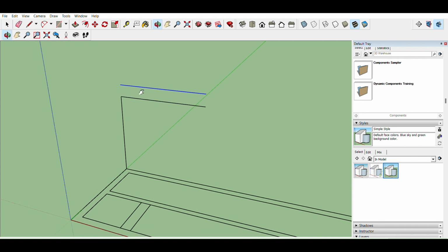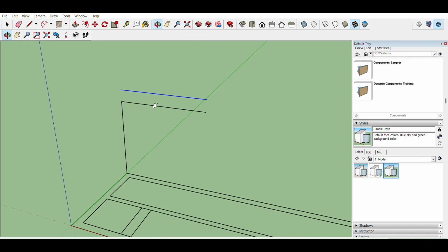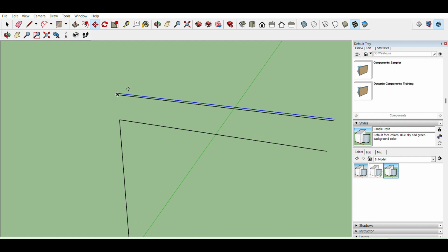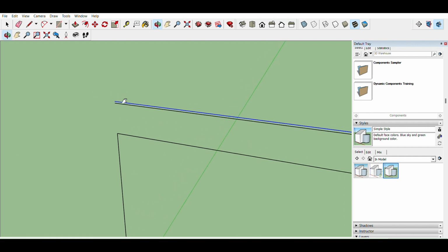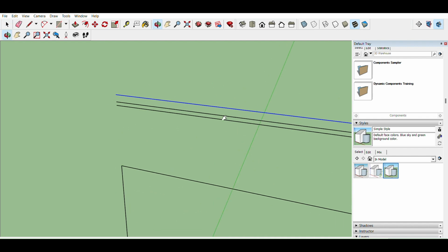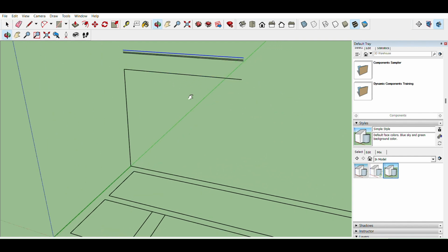And then, what's this building made up of? I'd say 3/4 inch plywood. Could be 5/8, but let's just go 3/4. And then I want to put a concrete topping on here. So, zoom in on this. Let's go another 1.5 inches. Okay, so now I've established the floor level, the floor to floor height from the first to the second floor.